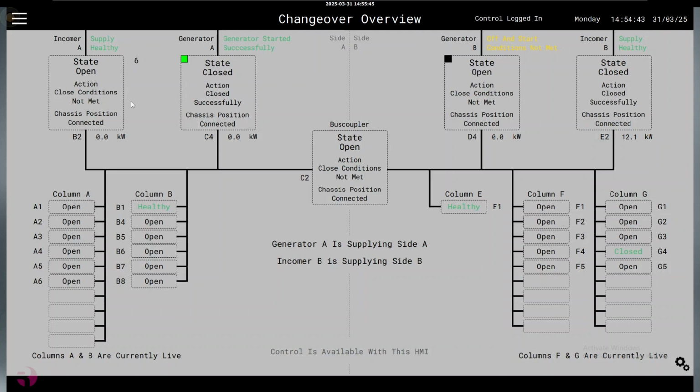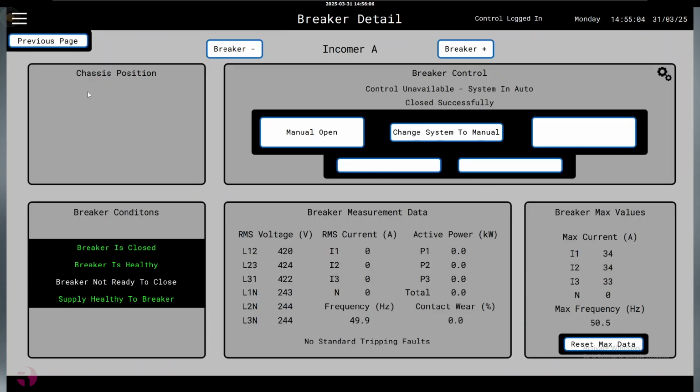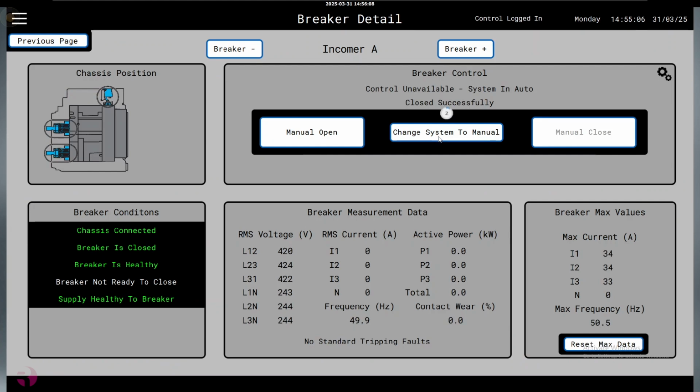As we said, this is one combination, but we offer a variety of different solutions using both break and no break changeover. A significant part of this solution revolves around remote switching of the incoming supplies. If we step back and ignore all of the automatic changeover, we're also able to manually switch between each of the supplies, including both electrical and software interlocking and conditions. We see more and more clients opting for this solution, making switching a much safer routine.